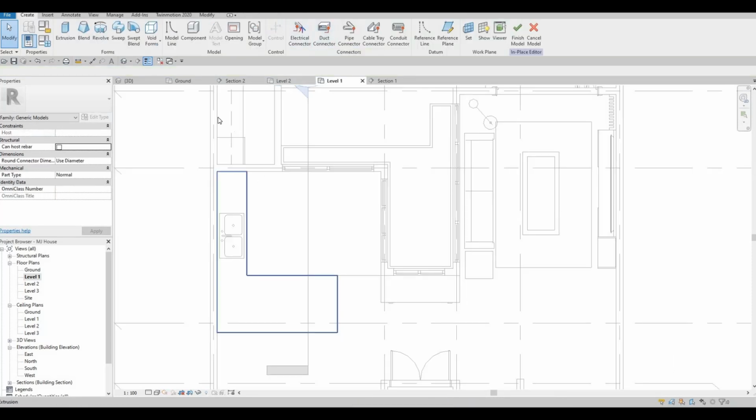The reason that we need to edit in place again on the specific one that we created before is because we are gonna void it. We can only do it on the void extrusion of that particular model in place, because if you keep on creating a model in place after a model in place, it will be very hard for you to void it, and it's not possible.